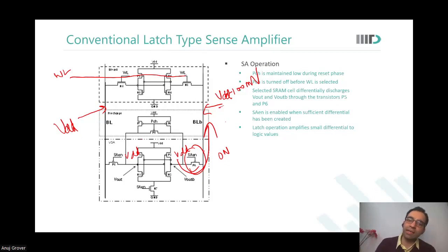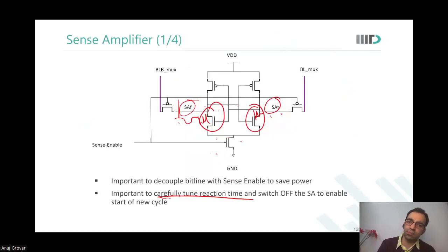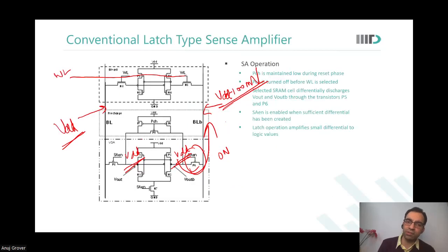You want to translate the differential on the bit lines onto the internal nodes. Is it that? Is it not? Yes. So you want to discharge the internal node, no? What's the problem there? That is your desired functionality. Okay, so where is the connection getting completed, sir?